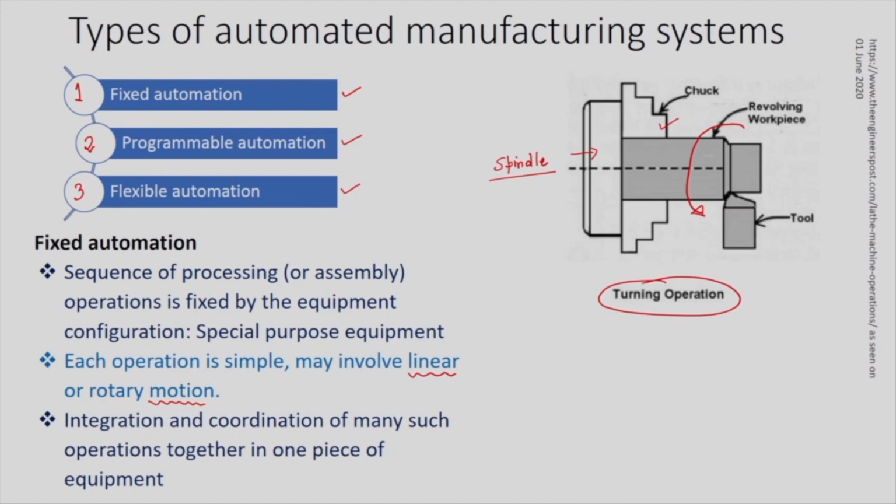So we are using a cutting tool. The cutting tool is harder than the workpiece. Generally at the shop floor we are using a high speed steel cutting tool if we are working on, say, a mild steel workpiece. Fine. So we are feeding the workpiece against the tool, but in this case, since the workpiece is rotating, it